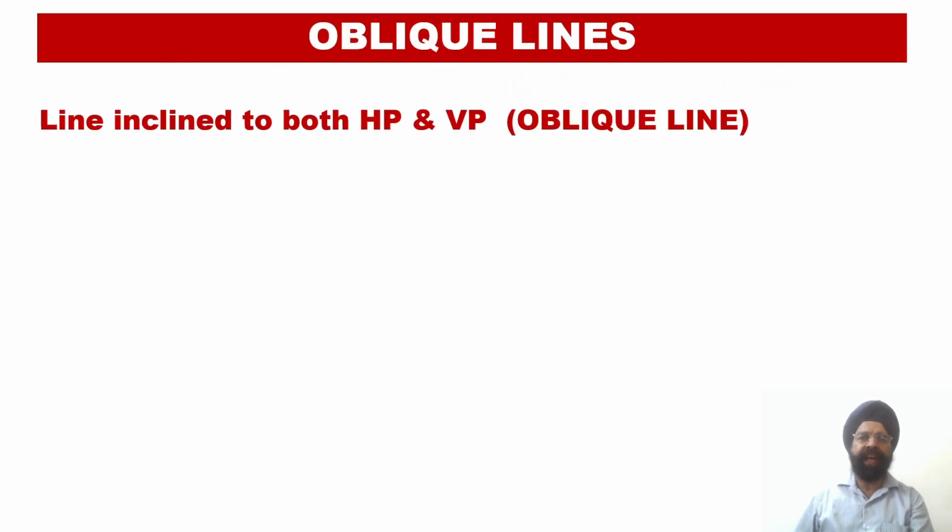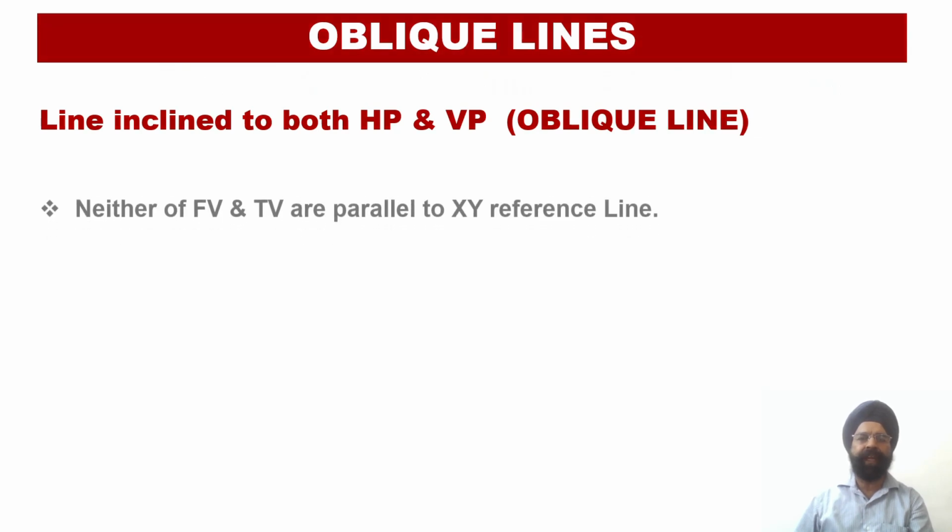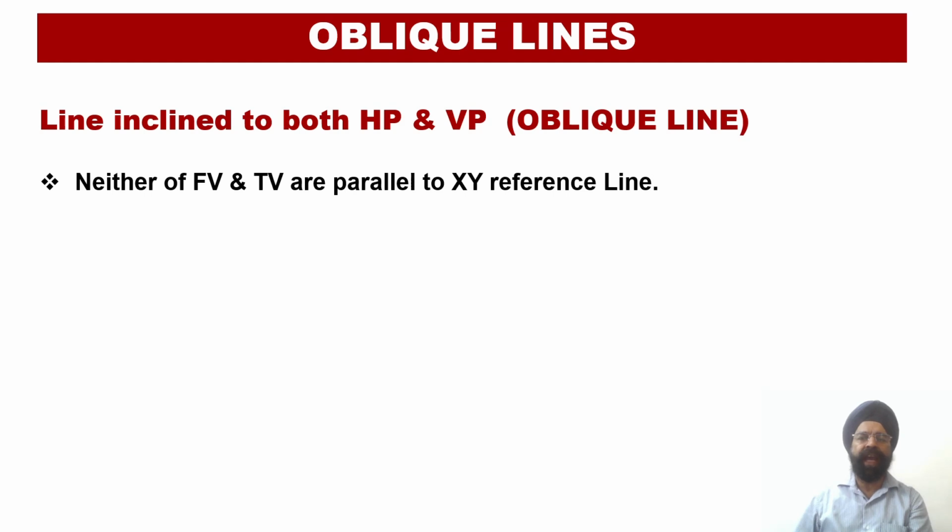Now, an inclined line is the one which happens to be inclined to both the horizontal plane as well as the vertical plane. Since this oblique line is inclined to both the reference planes, neither the front view nor the top view projections of this line will be parallel to the XY reference line.